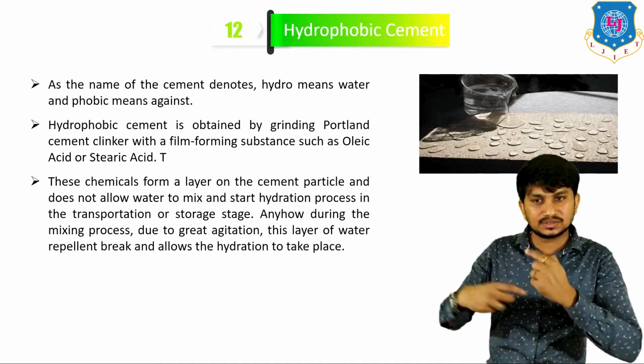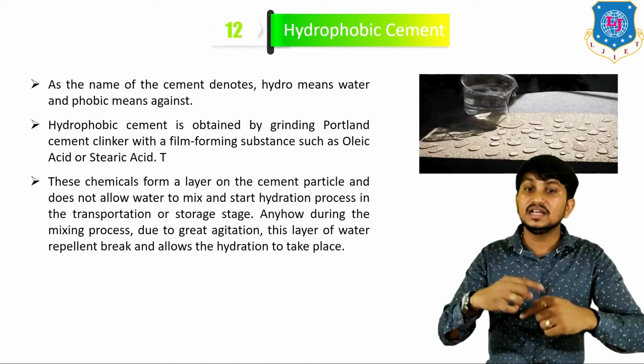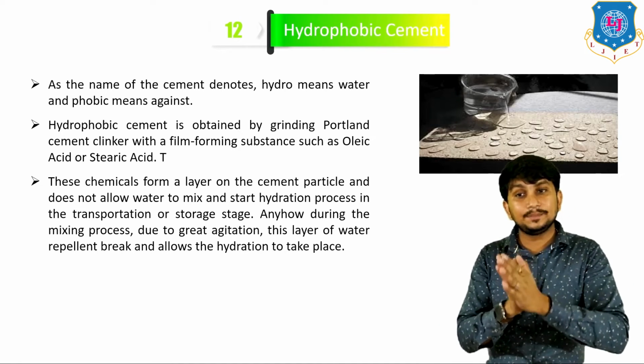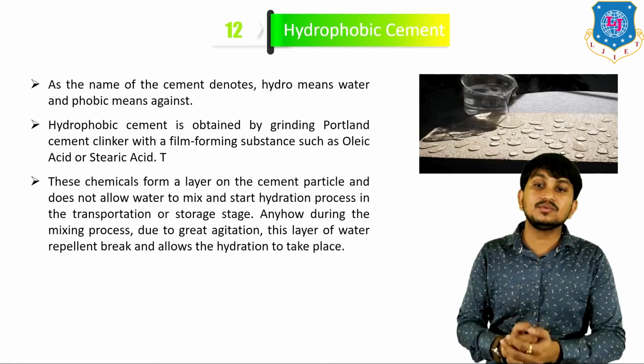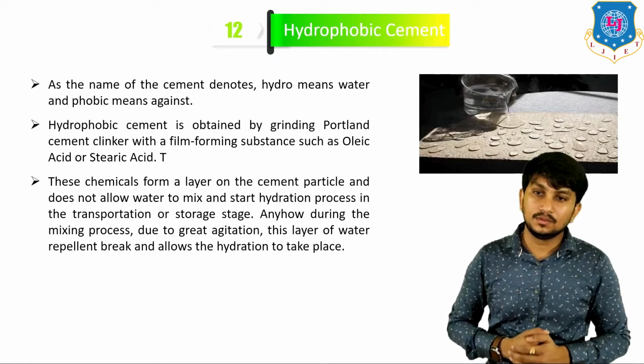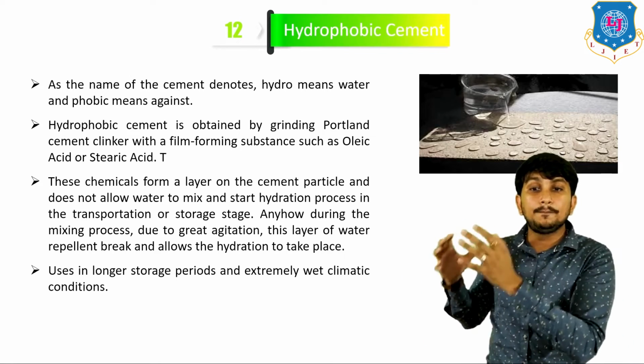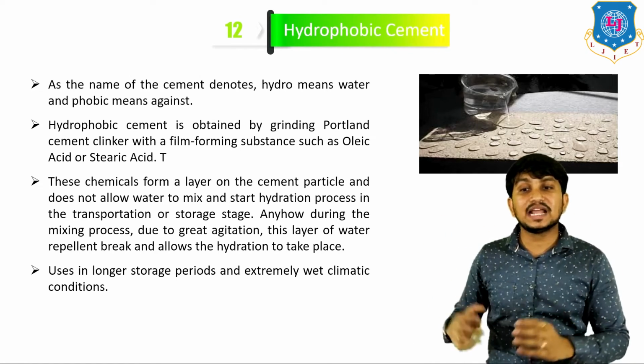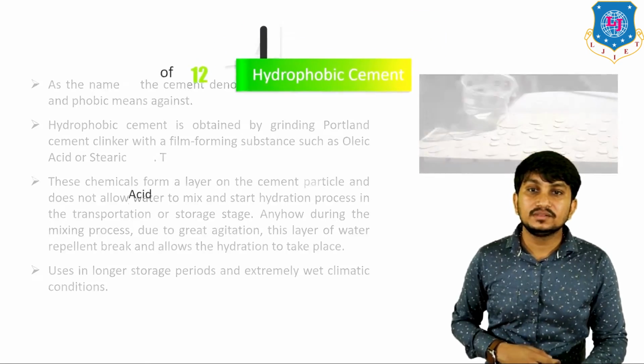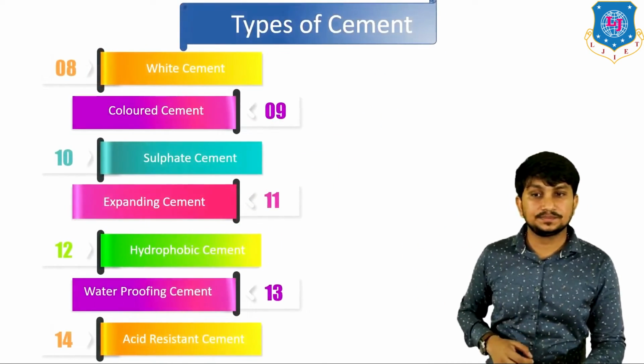However, during the mixing process, due to great agitation, this water repellent layer breaks and allows the hydration to take place. It is generally used in longer storage periods and extremely wet climate conditions. That's all about hydrophobic cements.